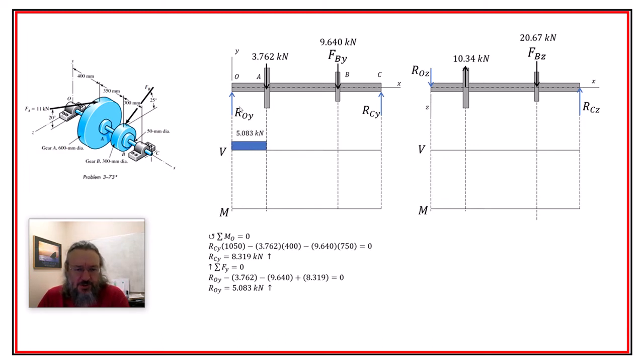So we have that first reaction creates this upwards shear, and then this force comes around as we're going from left to right, and doesn't go all the way down. Actually, it doesn't go below. This doesn't make it into negative. So there's a little bit of positive shear, not much. And then we have this other force, and that of course brings it back down.